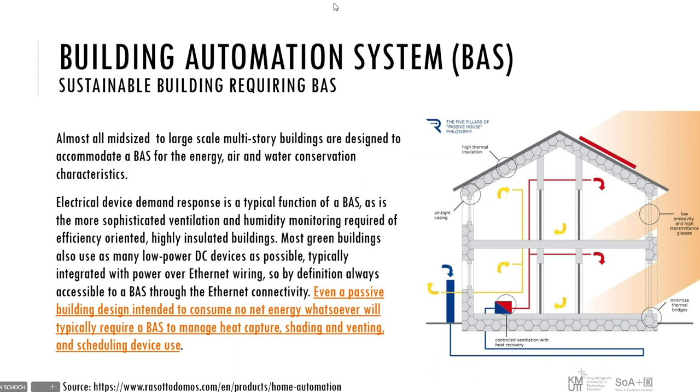And also the request for sustainability or for more energy efficiency is an important aspect of building automation systems, because with controlling and measuring, you can also optimize the amount of cooling or heating needs, as well as the amount of fresh air supply and the control of the equipment that is responsible for all these features.